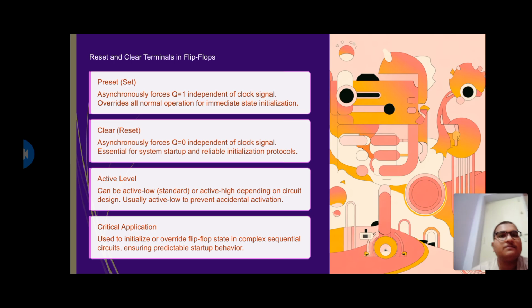Now, reset and clear terminals in flip flop. The set and reset states we have talked about till now. Preset asynchronously forces Q equal to 1 independent of the clock signal, overriding normal operations for immediate state initialization.